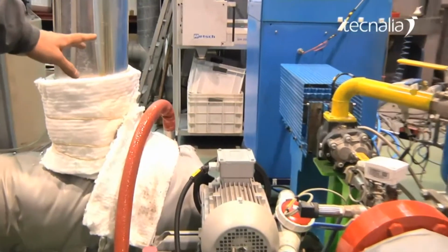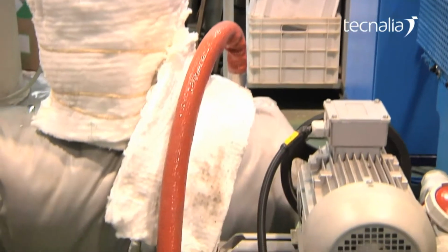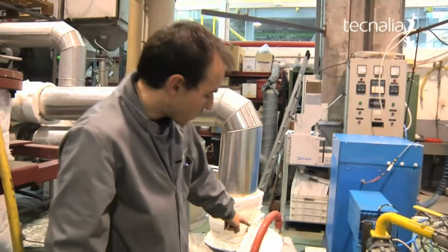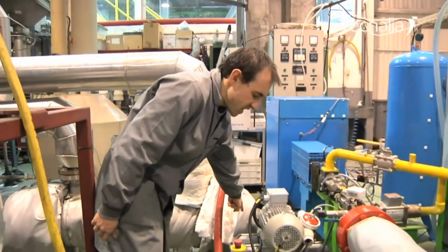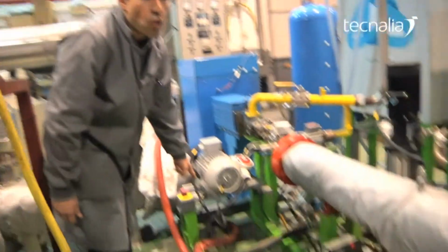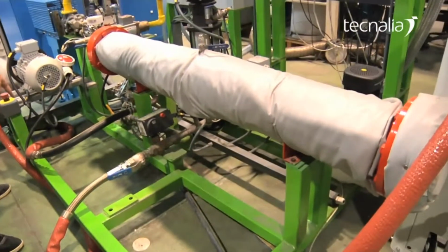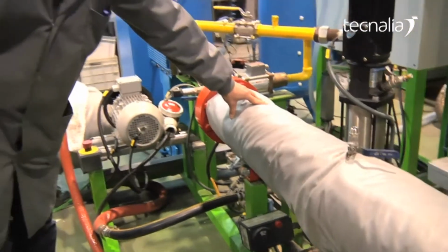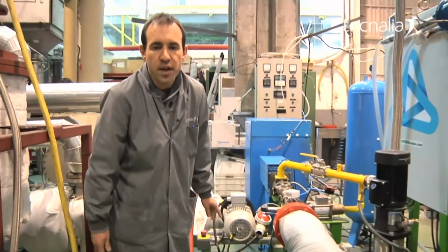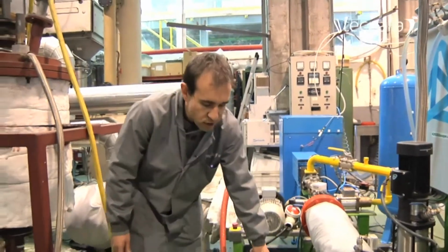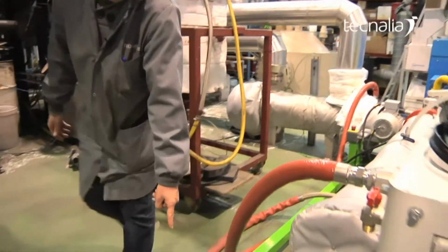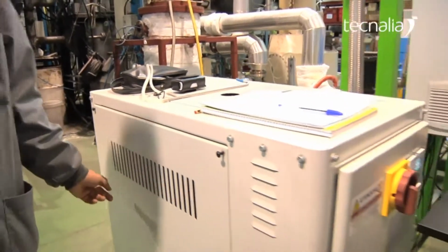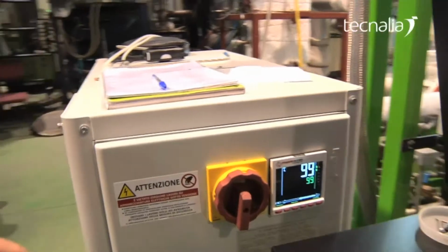And here we have the ORC unit. The ORC unit is activated with pressurized hot water. The hot water is exiting from the heat exchanger at around 105 degrees C, is entering into the evaporator where the heat is transferred to an organic fluid, and then the water exits the evaporator at around 90 degrees C and goes to the air temperature.